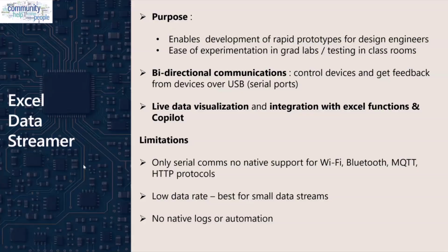The other important thing to call out is low data rate. Basically, you're talking about 100 hertz of sampling rate. Very important to keep in mind if you're doing high-speed testing or experimentation. So as an example, if you're doing ballistic armor and things like that, this is not the right tool for it because the rates are immense. You get into megahertz and so on and so forth. And then no native logs or automation. That's another call out. But those are all secondary.